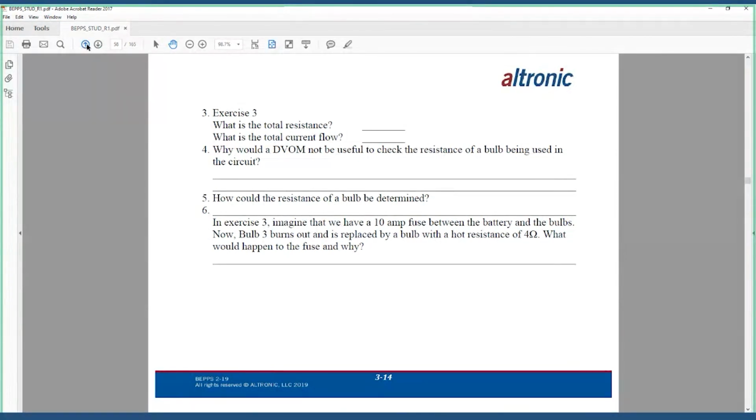The first rung had a 4 ohm resistor. The second one had a 6, and the third one had a 10. So what we did was we took 1 divided by 4 ohms, and it equaled 0.25. We took 1 divided by 6, and that equaled 0.1666667. I didn't round this time. And then we took the last one, 1 divided by 10 ohms, and we got 0.1.